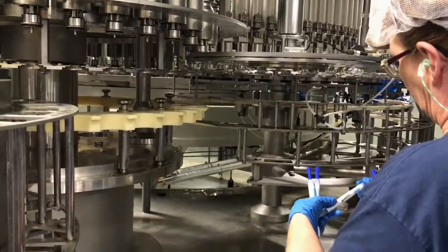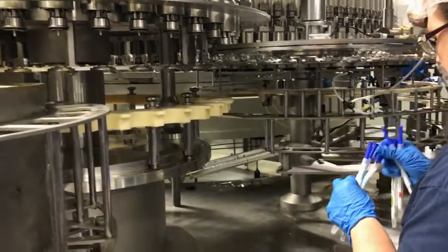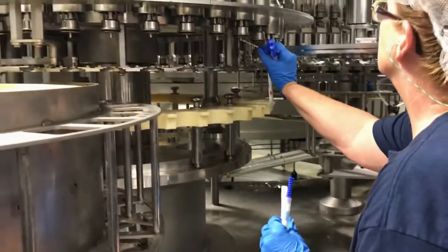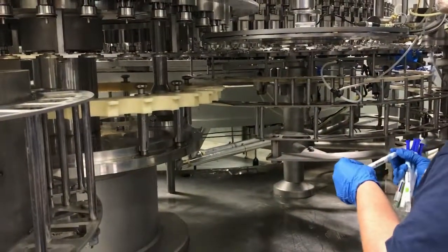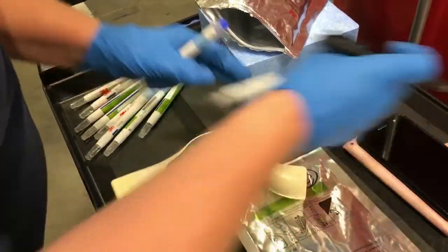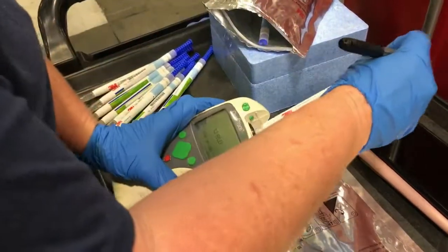After any maintenance work is completed, a pre-operation inspection needs to be done in order to make sure the line is ready to run again. This also makes sure the line is free of any lubes or tools that may be left over. There are also swabs that need to be done and documented to check for cleanliness before the line can run again. If you see any maintenance issues or have any concerns, talk to QA or a supervisor.